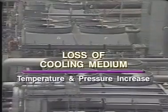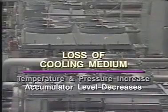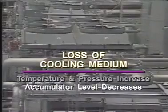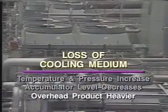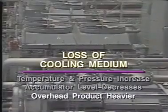When there is not enough cooling water or air going to the condenser, tower top temperature and pressure will suddenly increase. The loss of the cooling medium will cause the liquid level in the accumulator to decrease because hot vapors can no longer bind to liquid. A higher temperature also means that heavier material is driven up the tower, so the overhead product becomes heavier.